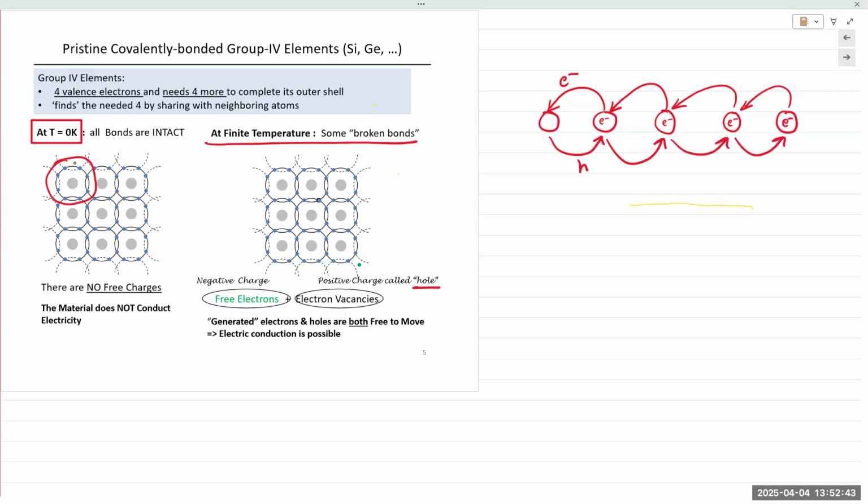As empty spots are created, more and more electrons could jump from spot to spot. It could just happen in a random, haphazard fashion. But the point is, as the electrons are occupying space, the holes are also being created at the same time. So electrons are moving, and at that same time, we can consider the hole to also be propagating. And for the purposes of analysis and entire semiconductor theory, we treat the hole as a particle in its own right, and we say it has positive charge.